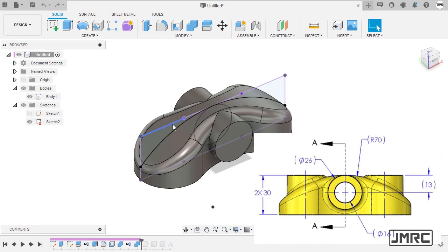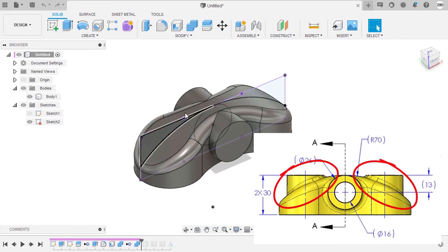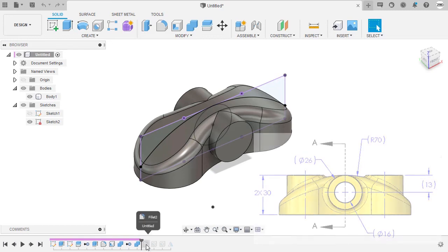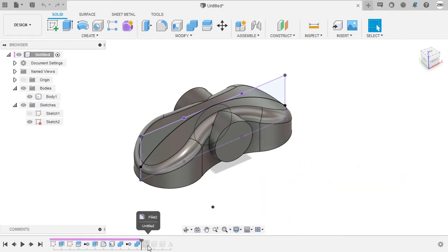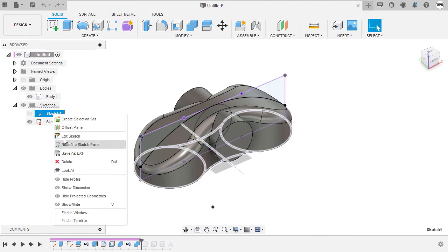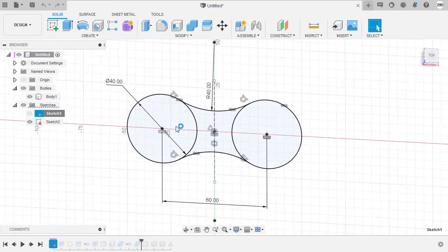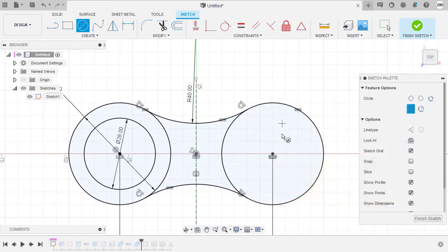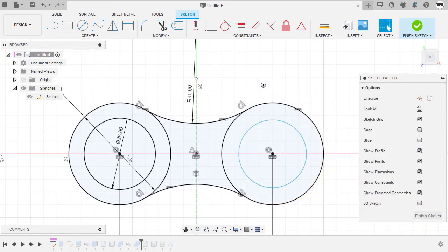Moving forward, let's focus on creating the cylinders on these faces. And recall, the edges of those cylinders will be having a value same with this fillet too. Let's now head over to our sketch 1 and add that circle. Selecting edit sketch. Hitting C for circle. Let's drop our center point at this center point. The radius to be 28.